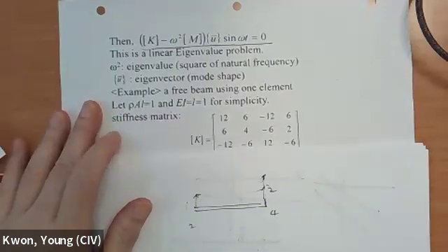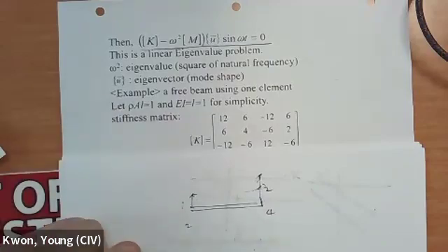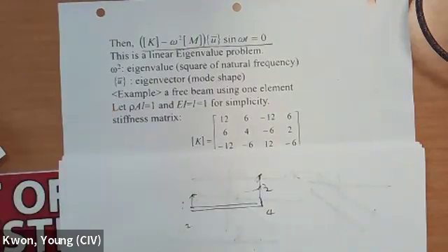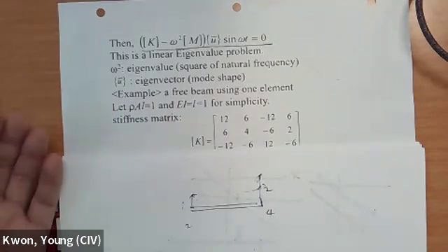I'm not suggesting any kind of impact loading or mechanical way to check the natural frequency. You listen to music. When you listen to music, what rhythm is your body going to move to? So we are looking for the resonance, right? When you excite the system with different frequencies, when the excitation frequency matches the natural frequency of the system, then the system is going to have resonance.